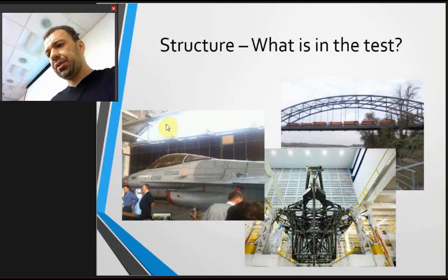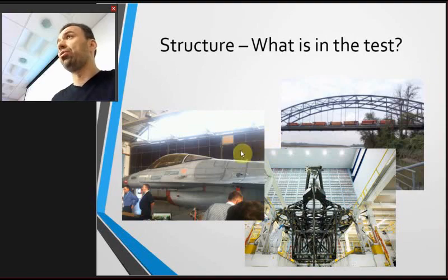Okay, what about this jet plane? Being a fighter jet, you need to be aware of what's under the wings. So what configuration are we testing? What's the status of the fuel? Have we full, quarter full, empty tanks? What's generally inside, what's not? You're gathering modal data of the structure, so you need to connect it to the configuration of the structure.